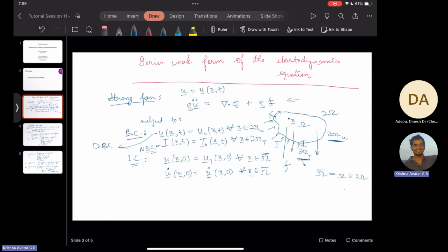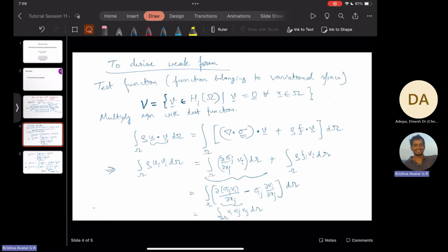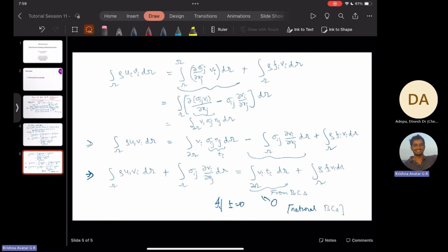So what we see here is we had to clearly define our variational space with the Dirichlet boundary condition, that it has to satisfy Dirichlet conditions. For Neumann boundary conditions, it followed as a result of the process. That is how I learned it, but there are different approaches, like what Belytschko and others do: they will even add the boundary conditions as a part of the variational form using some penalty approach, and then they will reduce that.